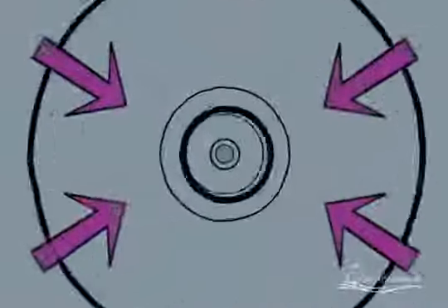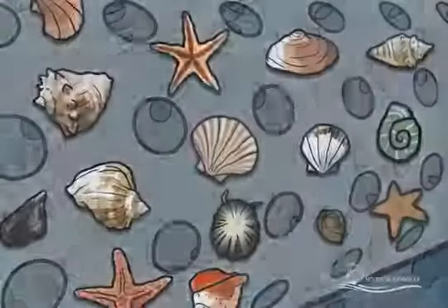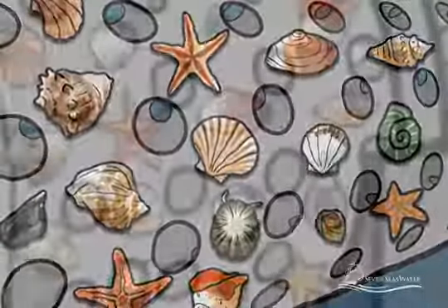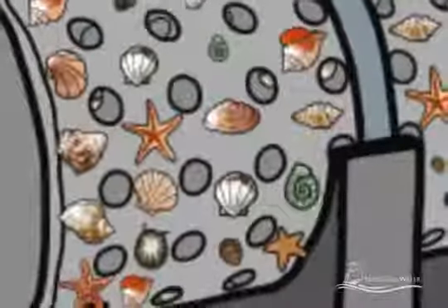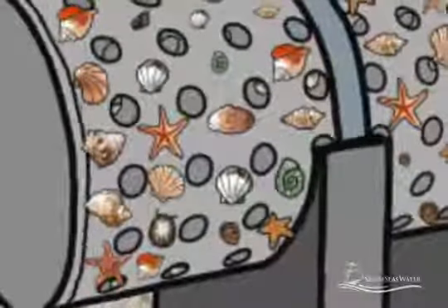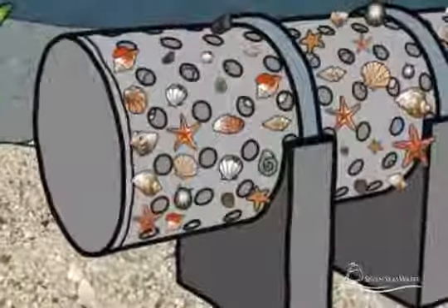The concentrated salt stream is sent back to the ocean through a brine disposal well, or a device known as a brine outfall. The brine outfall is situated in an area of significant ocean flow so that the salt levels are quickly returned to equilibrium with the ocean. The location for the outfall should contain no sensitive marine ecosystems.